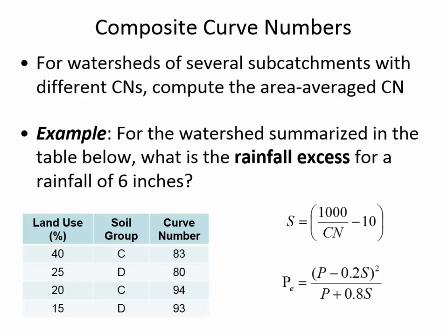In the homework, you want to know what the runoff volume per unit area is. Well, this is the runoff depth per unit area. If I wanted to know the runoff volume per unit area, I'd say this depth times an acre, which is 43,560 square feet, converting from inches to feet. And so I could find a volume, meaning cubic feet per acre. This isn't yet a volume, this is a runoff depth. Does that make sense?